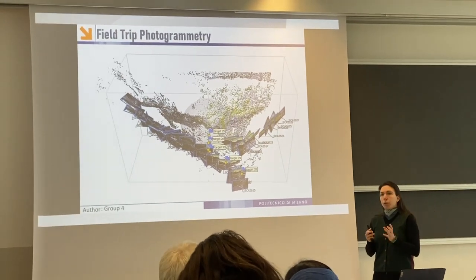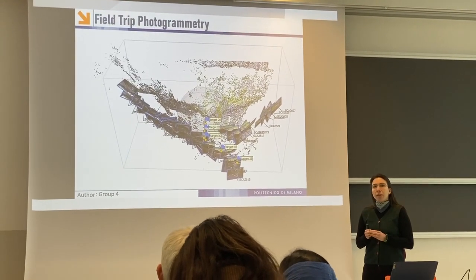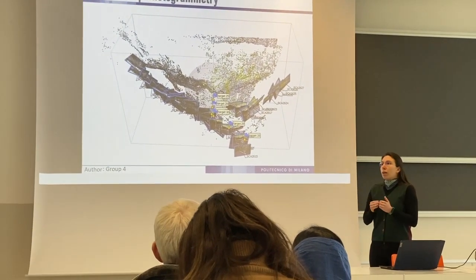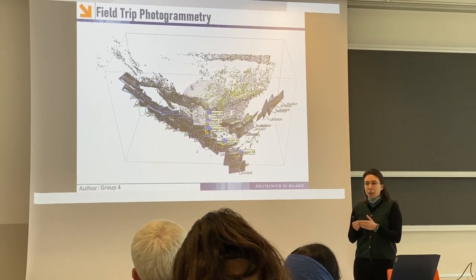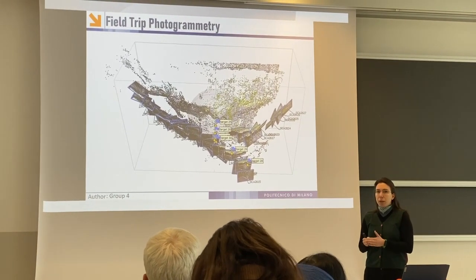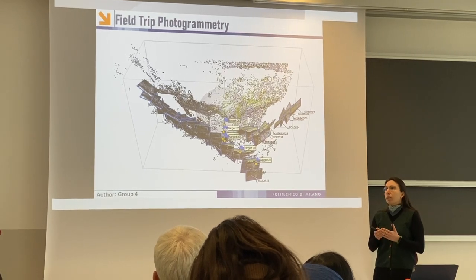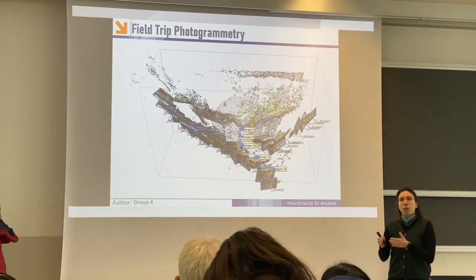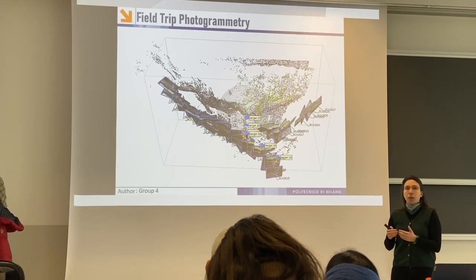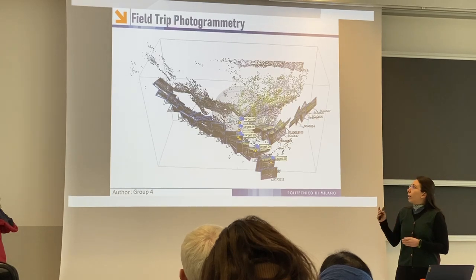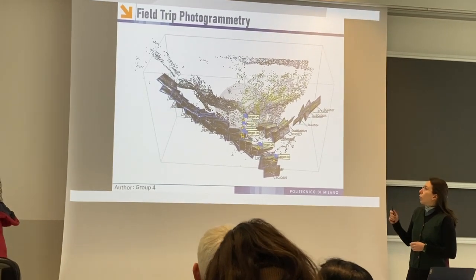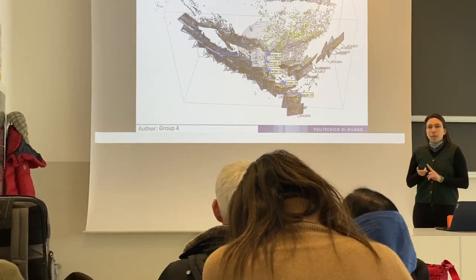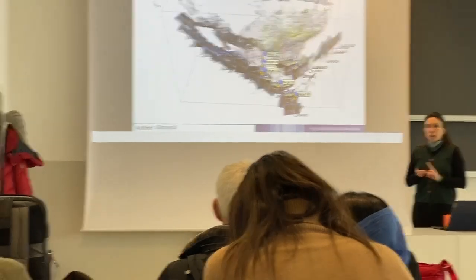At first, we took pictures in our field area to process them in Metashape. When we uploaded our photos to Metashape, we had to follow some specific steps in order. The targets are detected automatically on Metashape. However, we also have to do this detection manually to avoid using any wrong ones. And then comes the alignment of the targets. After the photos and targets, the bars are scaled by optimizing the cameras.